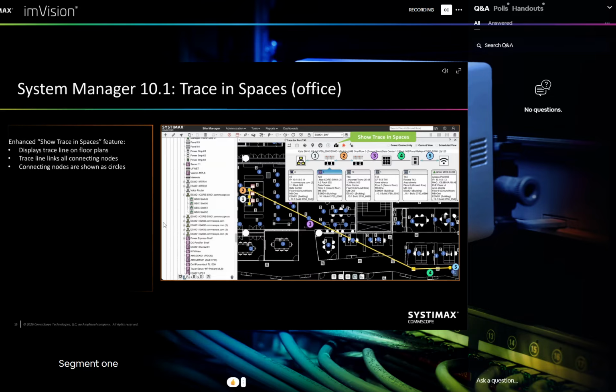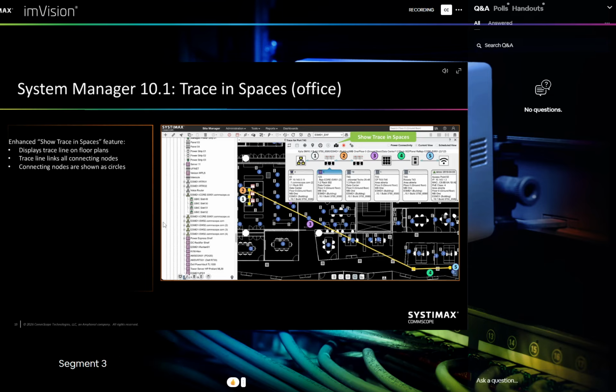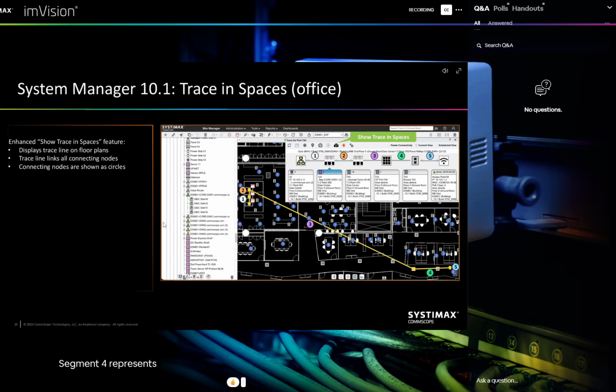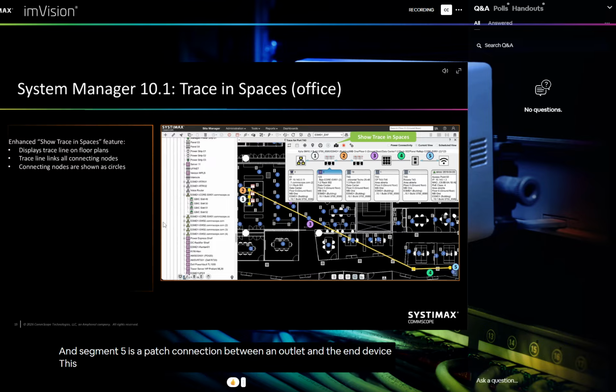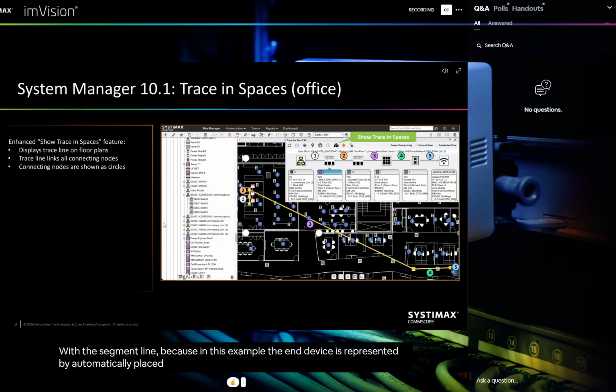Segment 1 and Segment 2 connect the switch and patch panel ports installed in equipment racks. Segment 3 represents a cable connection between the patch panel port and the port on the consolidation point. Segment 4 represents a cable connection between consolidation point and outlet on a faceplate. And Segment 5 is a patch connection between an outlet and the end device. This segment is not shown with a segment line because in this example, the end device is represented by automatically placed device badge positioned next to the faceplate.